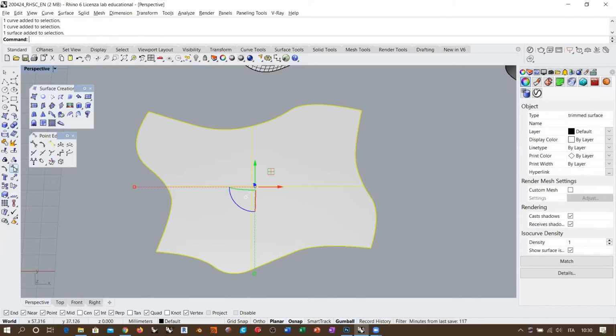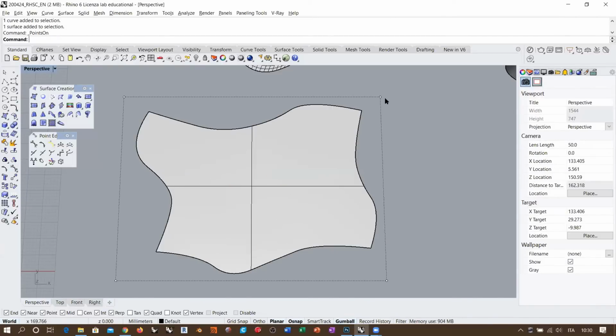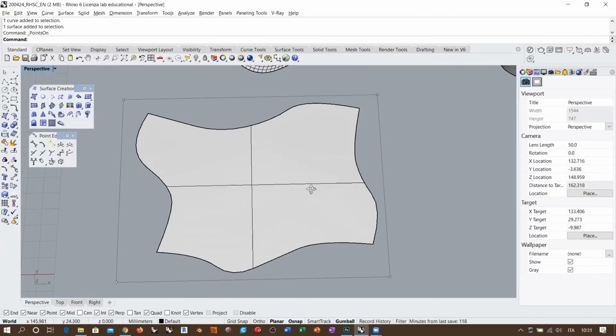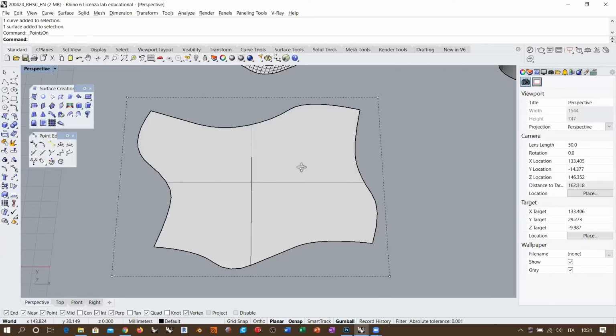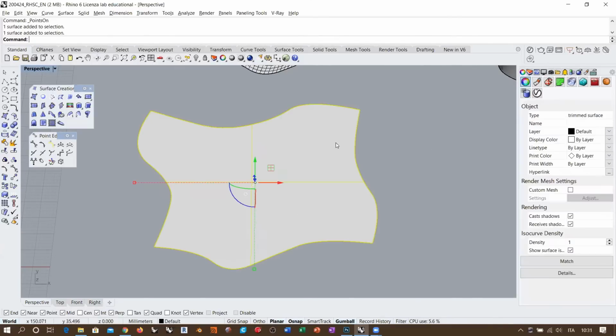So if I activate the control points, I see that the actual surface reaches this outline here, which is the rectangle. And then this rectangular surface is being trimmed with this silhouette here. Now, this being a rectangular, trimmed surface, it means that its topology does not correspond exactly to the boundary of the surface that I see. So trimmed surfaces are, let's say, a visual operation where you see the final result, but the topology stays untouched, right? So being a rectangular surface, it has no deformation possibility on the inside, because there are no internal control points.